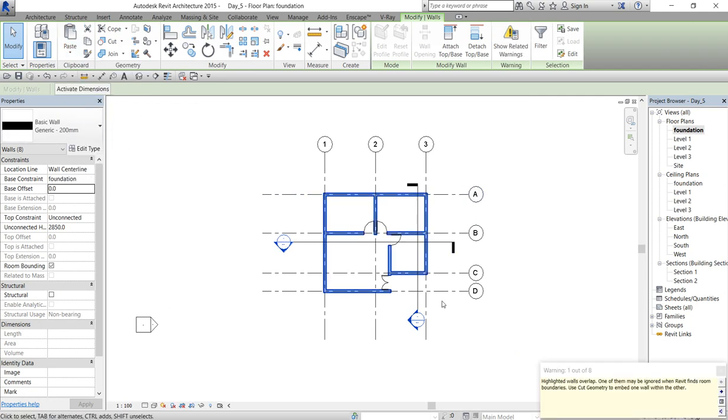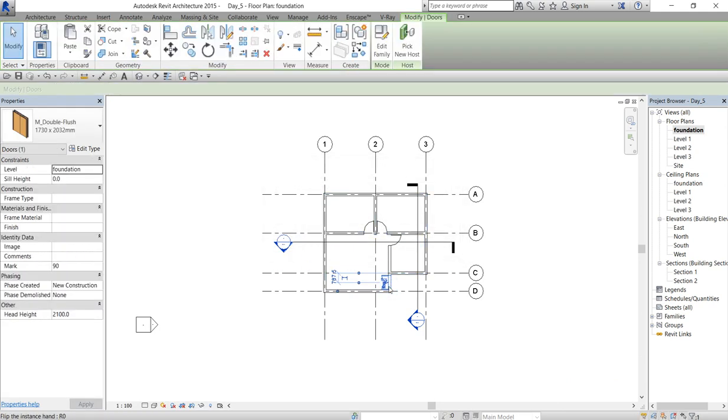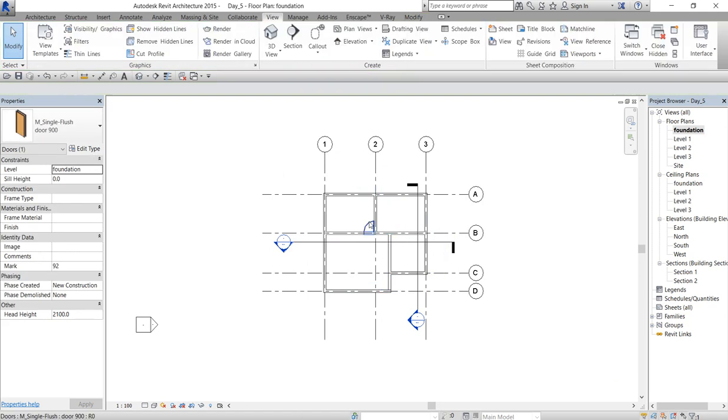Be placed there, but don't ever let it be this manner. So as you selected blue, come to this place and change the height to normal height. Calculate it very well before you do this one. Remove the thickness of the floor out of that. So from the 1000 of the level, let's say we have 800 millimeter. So click on it. You have to say yes, delete it. All those ones that are not needed, this window has gone. Then this door, delete them on this floor.